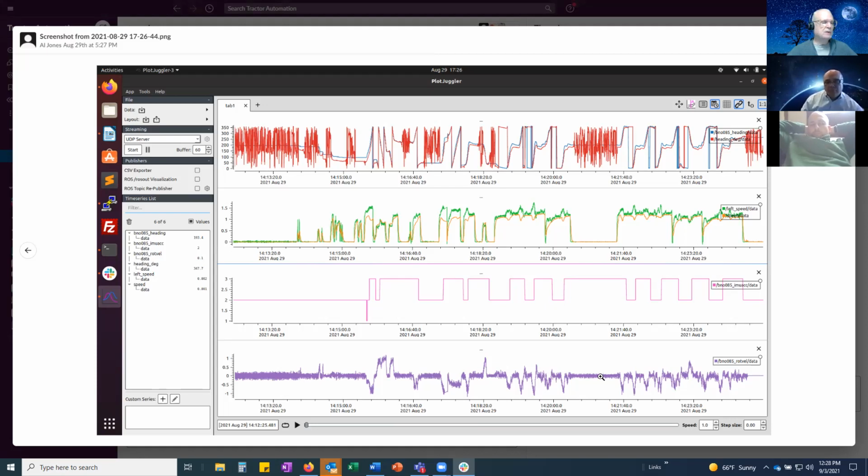As far as your mounting, keep in mind that due to the vibration and the resonance, depending where you go on the vehicle, you're going to find higher vibration at some points and lower vibration at some points. It might be worth poking around and finding somewhere better. You could probably just put your hand on it while it's running and feel it. And if it feels like it's vibrating a lot, touch somewhere else, maybe right on the frame, and see what it's doing. So you might just get better results by mounting it somewhere else, was my point. Yeah, that's a good point. I'll try a couple places and see what sort of vibration I get.